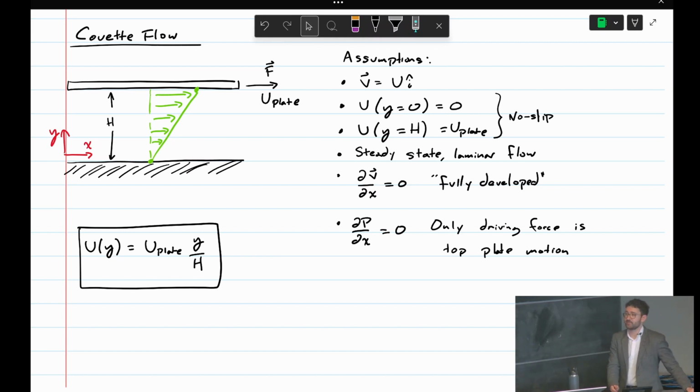That's a really good question. The question was, are we assuming that h is sufficiently large so we don't get a boundary layer there? You'll learn more about that on Wednesday's class. This is actually assuming that h is quite small so that there's no boundary layer that forms. This generally happens at very, very thin layers in fluid. You get this very special Couette flow. So that tells you roughly the scale you're dealing in. But if you don't understand what a boundary layer is yet, that's okay. We'll talk about that on Wednesday. Any other questions? Okay.